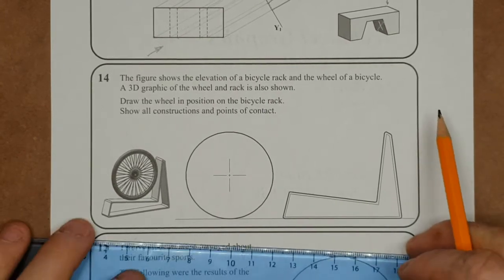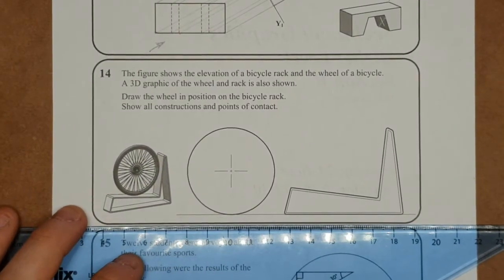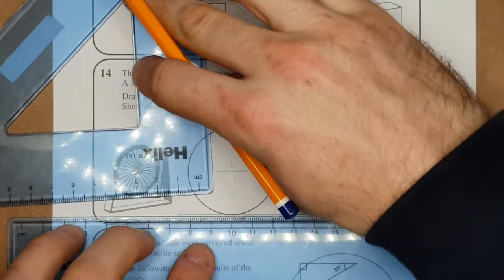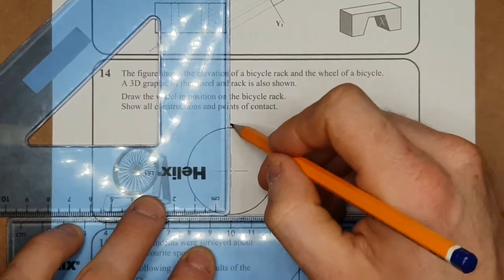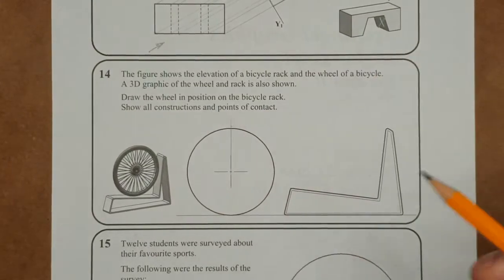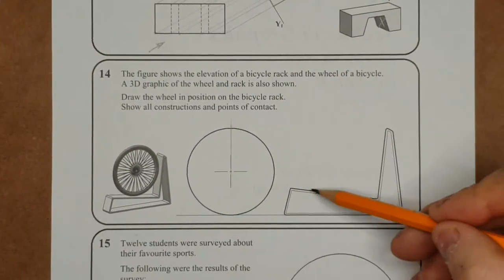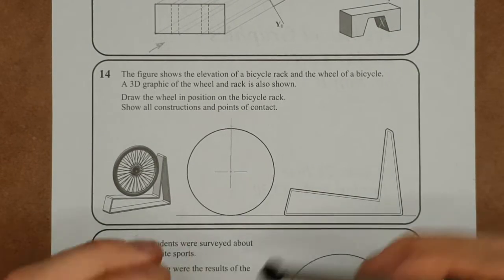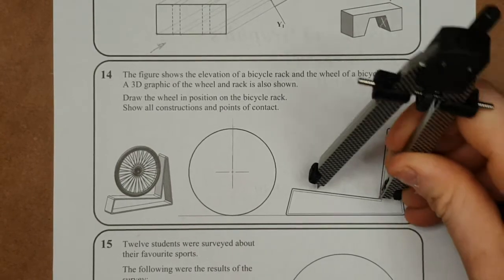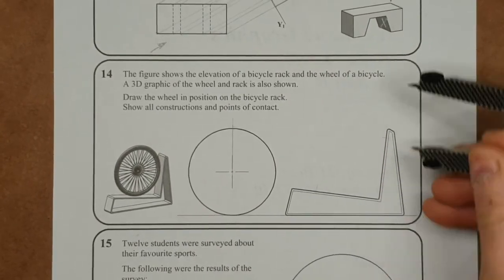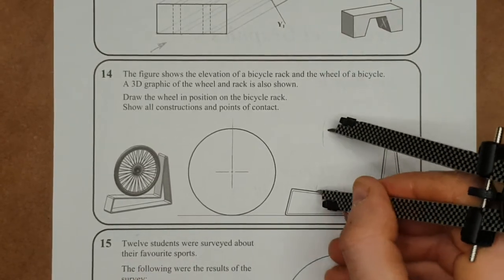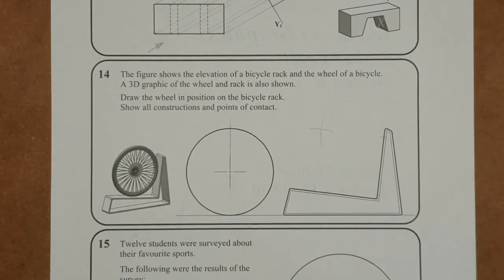First thing I'll just do here is take the base angle, just so that I can get a perfectly accurate radius of what's happening. I'll just draw a radius line from the center out. First thing, if I'm putting any circle in to touch two lines, I'm going to bisect the angle because I want to see exactly where it touches both lines. We can just take it that that's the corner. So set your compass to a random size, strike your 2 points, and then strike again from both points. So there's my angle bisected.